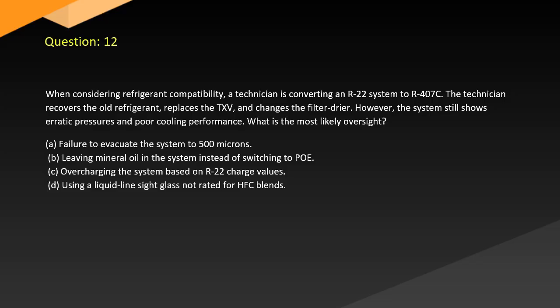A. Failure to evacuate the system to 500 microns. B. Leaving mineral oil in the system instead of switching to POE. C. Overcharging the system based on R22 charge values. D. Using a liquid line sight glass not rated for HFC blends.